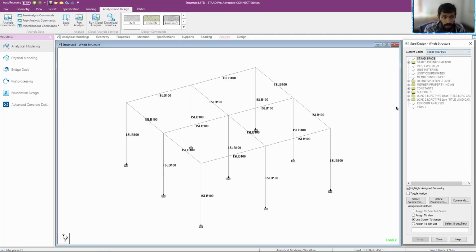Alright, the first thing that I would like to do here is I'm going to optimize the section by providing multiple ratios. In the normal case, we'll be providing a single ratio. Okay, ratio 1, analyze it. It might not utilize the section properly. Maybe the ratio might be less than 0.5, or maybe it might fail. So I'm going to perform analysis based on multiple ratios.